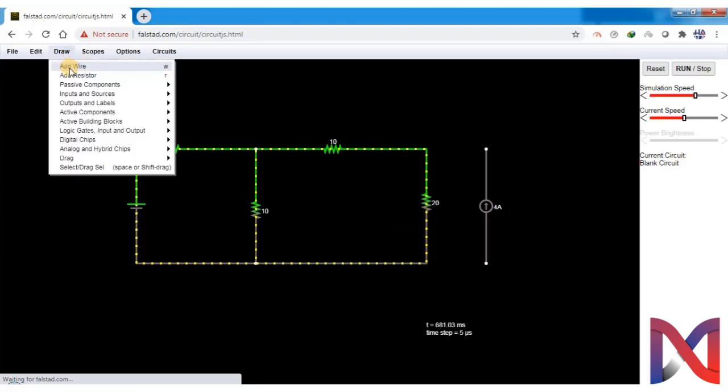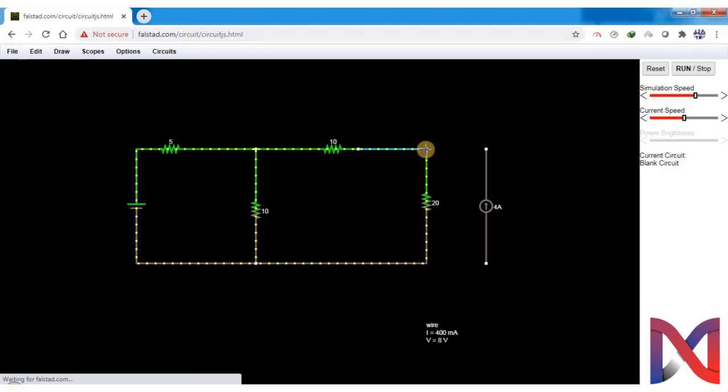We will connect the current source as well. So this is how our circuit looked. Now, according to the superposition theorem, we have to take the impact of one source at a time. So either we have to kill the voltage source first or the current source first. So we will proceed as per our example.